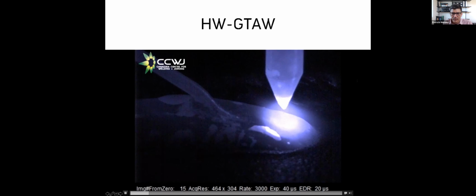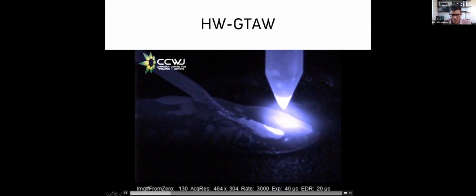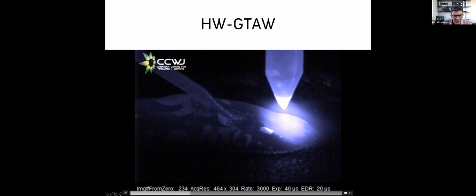Here we have our tungsten electrode, and by now you see, 2 days ago, some of you didn't know what TIG meant. Now we're talking about the subtleties of the electrode. The arc is coming in here. Here we have the weld pool, but the interesting part is this, you see here on the left. And you see it's kind of faint, but it's somewhat lighter, an amount of wire that is coming in. And you see how it's melting in?